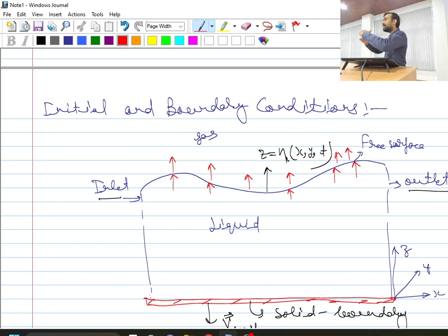If you say that in vertical direction, gas and liquid are moving at different velocities, then you will be getting some void space at the free surface, which is not feasible under practical circumstances. So it means that whatever velocity the free surface is rising up or down with, the gas above or below will have the same vertical component of velocity. I am referring only to the vertical component of the velocity.